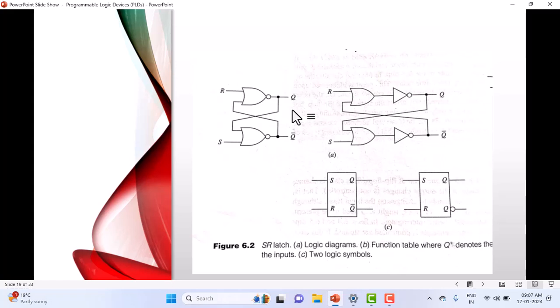Just like here you see, we started with what? 1 and 0. To arrive at the stable state, I took almost 3 states, right? I progressed through 3 states. Then only I got the stable state here. Understand here? So that means when you apply an input, you should not come to a conclusion early; at least you should analyze for 3 states. You will get to know what the stable state is.